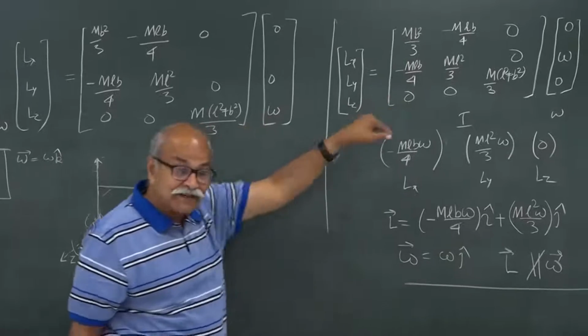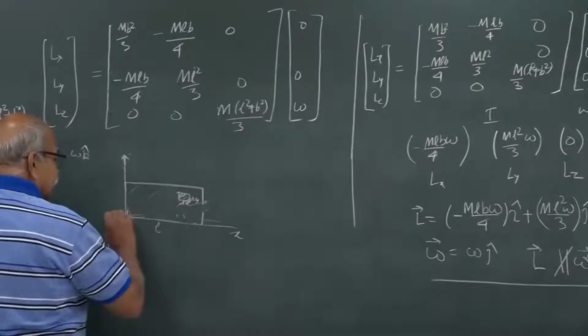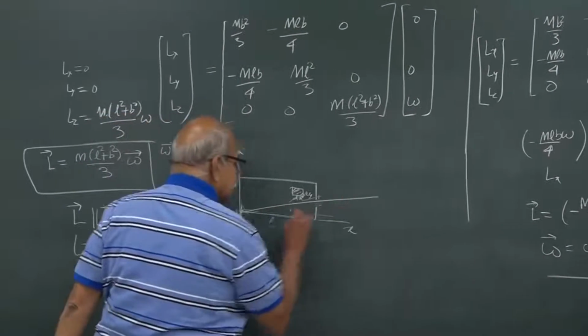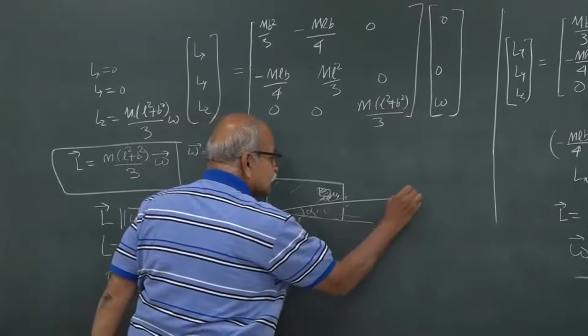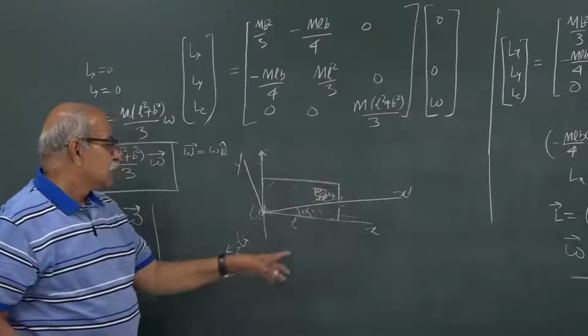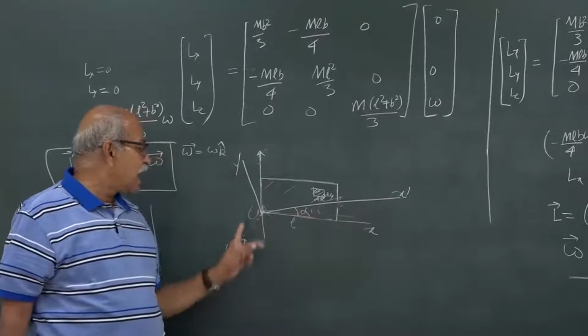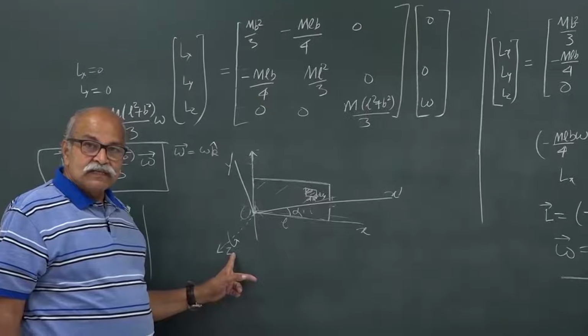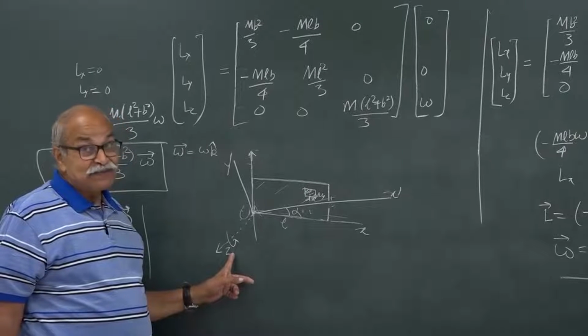You can find that and this will be your homework. It must be in this plane. So, suppose it is at some angle alpha, this is say x prime and this is y prime in this plane. If these are principal axes, then the product of inertia term should be 0.